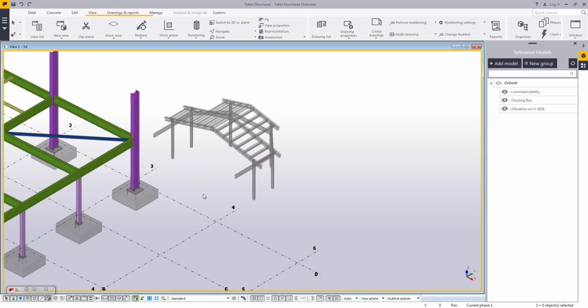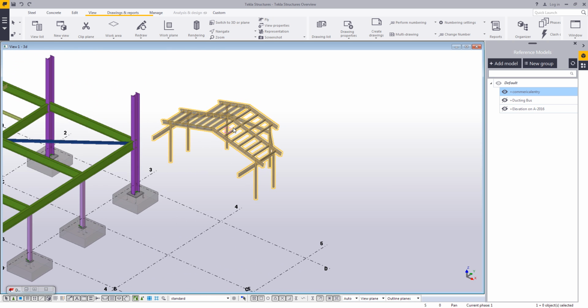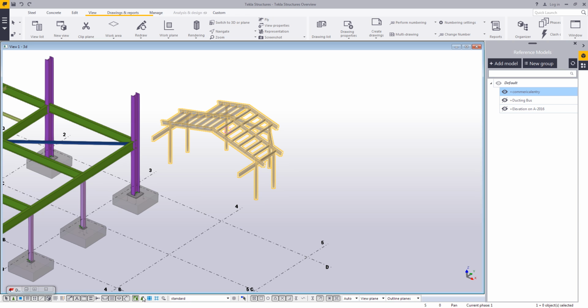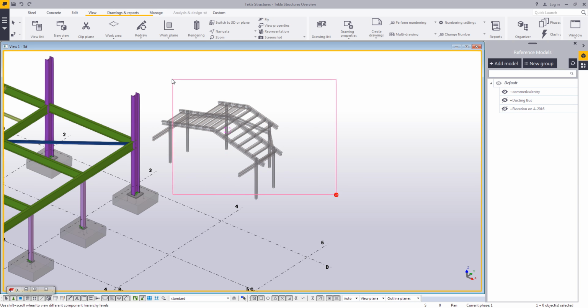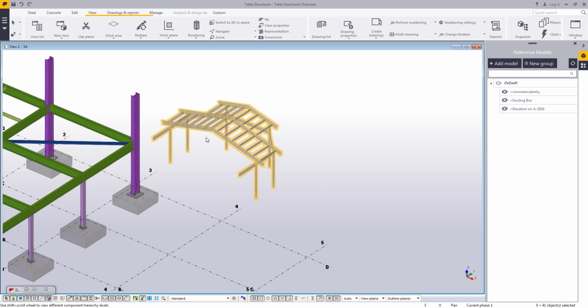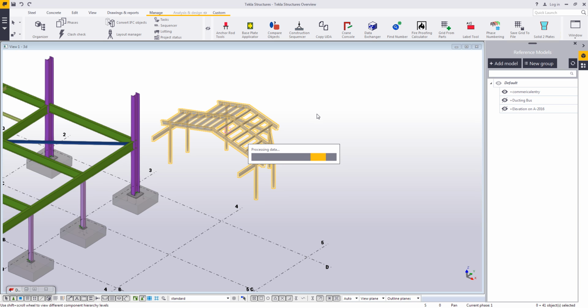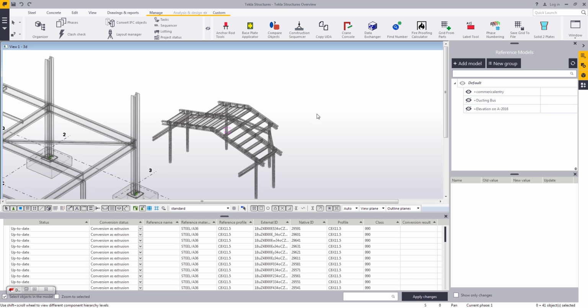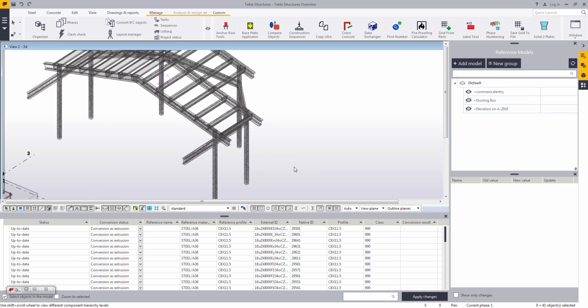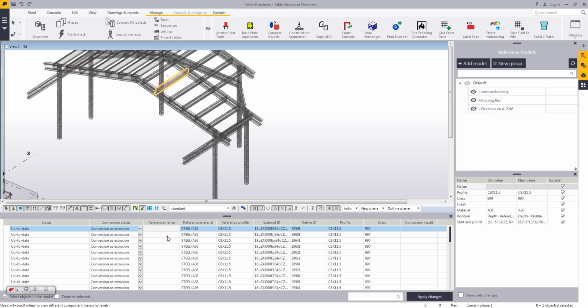This can come from a design software or another detailing package, but then this solid reference can be taken a step further. Because this is a smart type of file, I have the ability in Tekla to convert these objects into native Tekla parts with a single click. So it's going to find and recognize what those shapes are and then automatically convert them into native Tekla shapes.